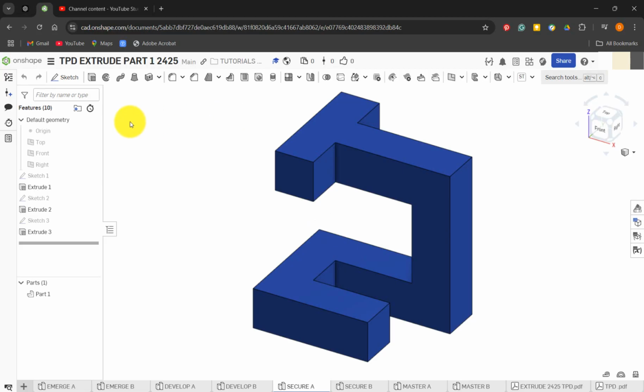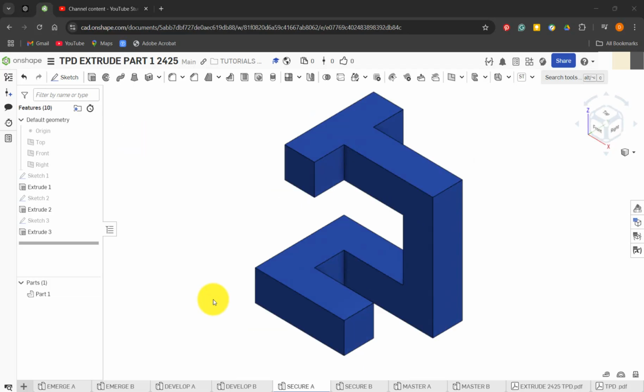If you don't have the options at the top of the screen like this, you will see some similar symbols there and along the bottom. What you need to do is go into this area here and go copy workspace, save that into your own ONSHAPE account or in your ONSHAPE area, and then you can obviously edit that and you can share it with anybody you want. So the first thing to do is click on the plus, select Create Part Studio.